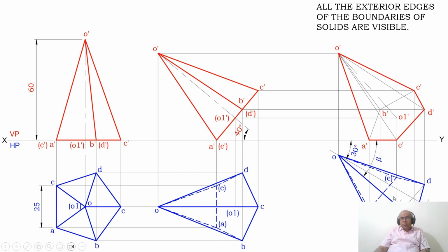So, since the inclination given to the axis is 30 degrees, which is the true inclination, but what I have for O1 in the second position top view is the apparent length, therefore I need to find out the apparent inclination here. So, how to do that?